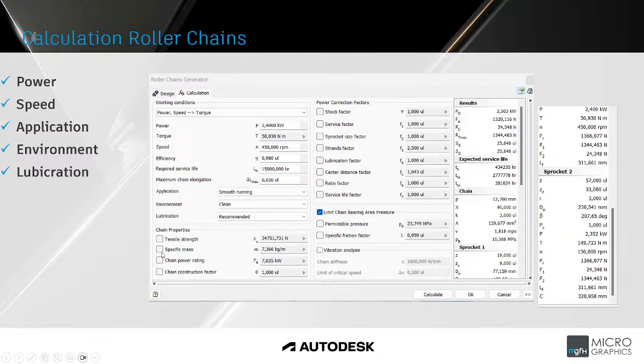With the chain properties, I didn't add anything specific here or by the power correction factors. I ran the simulation and I calculated it. So Inventor ran the calculation for us. As you can see with the results, it's quite nice because it can actually go up to 2.5 kilowatts. That's also quite a nice and handy tool to have with the calculation.